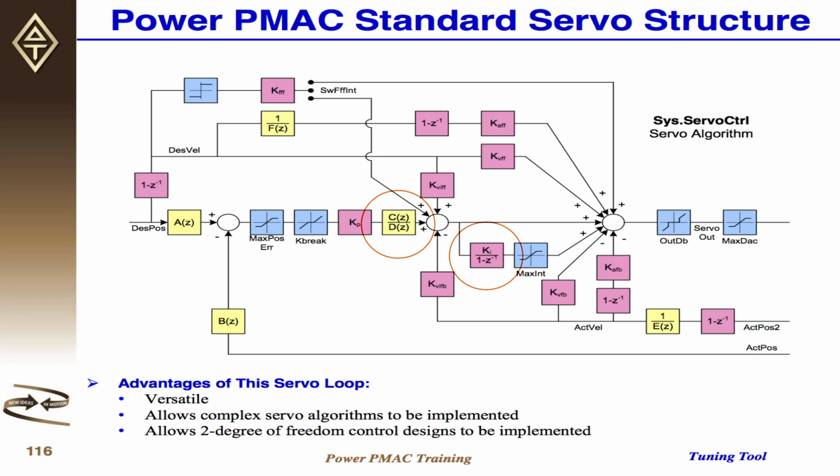You can also have a velocity feedback inside through the integrator, which in some cases is useful so that you have a better response in terms of velocity. So they are different. Typically you use either this or the other one. And you will see we also have an acceleration feedback. In some cases this is really useful.